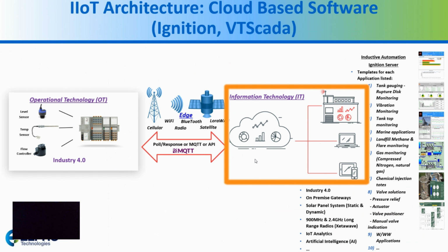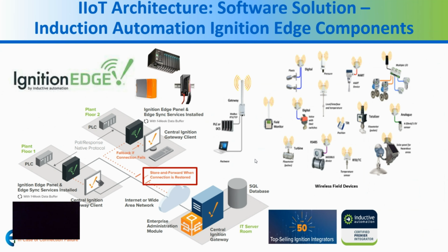Up in the cloud, as it's considered the IT, that's where Ignition or VT SCADA would reside. It has a driver built into it to communicate MQTT, where other manufacturers may not have that protocol built into it. But they're software companies, so they develop it to where you can. And the advantage of that is what I just mentioned with the namespace, and being able to have that keep alive connection to where you have the stale data.